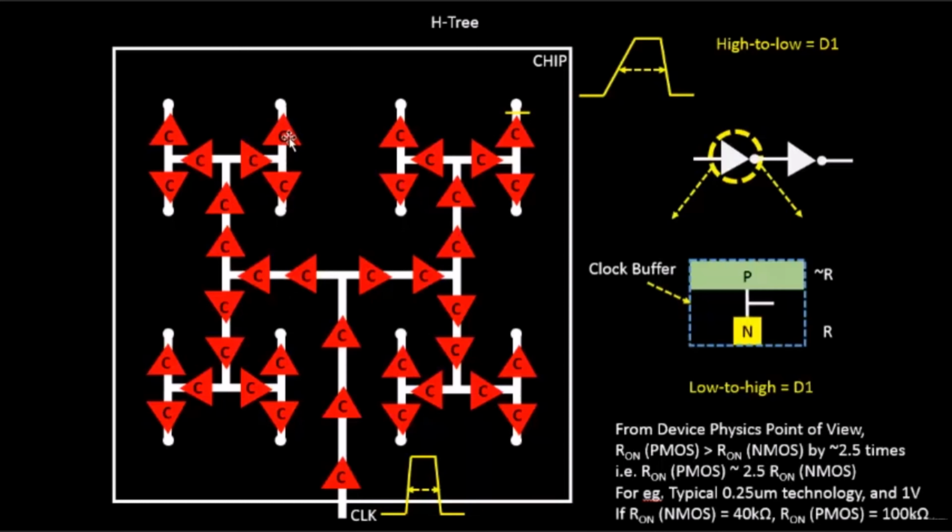Now after swapping with clock buffers, basically you're touching the clock tree. So once you touch the clock tree, the complete analysis, the complete quality check, needs to be done again. For example, we can skip the skew part, and the reason is, let's say we calculate the skew between this point and this point.